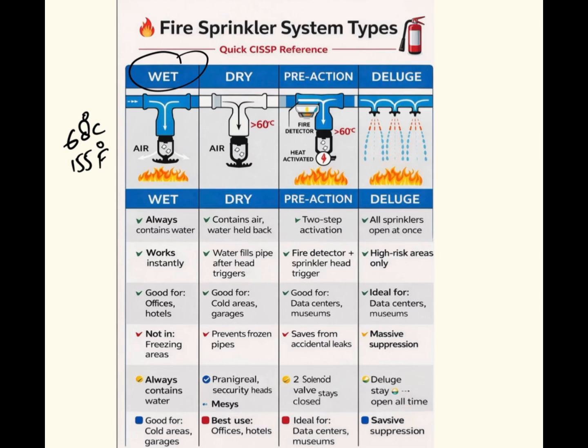Key strength: simple, reliable, and the response is very fast because it is wet. The water is always filled in the pipes, so therefore the response is very fast. The risk could be accidental discharge. If there is a false positive, then it could be accidental discharge, and that could cause big damage. Not suitable for freezing areas.